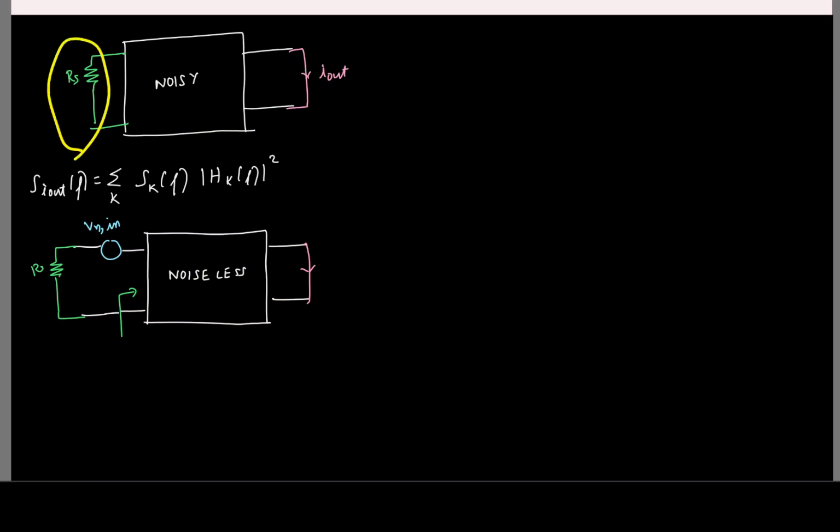The issue is coming because we are trying to model the noise in the output using something at the input, and obviously this voltage source alone is not enough. So what did we do? We also said we need a current source, and I call that In,in. Now both of these together capture the effect of the noise, so that irrespective of the source resistance you get the same total noise at the output. Both this voltage and the current noise capture the effect of noise of the same network. So do you think they will be correlated or uncorrelated? Correlated. They will be highly correlated.